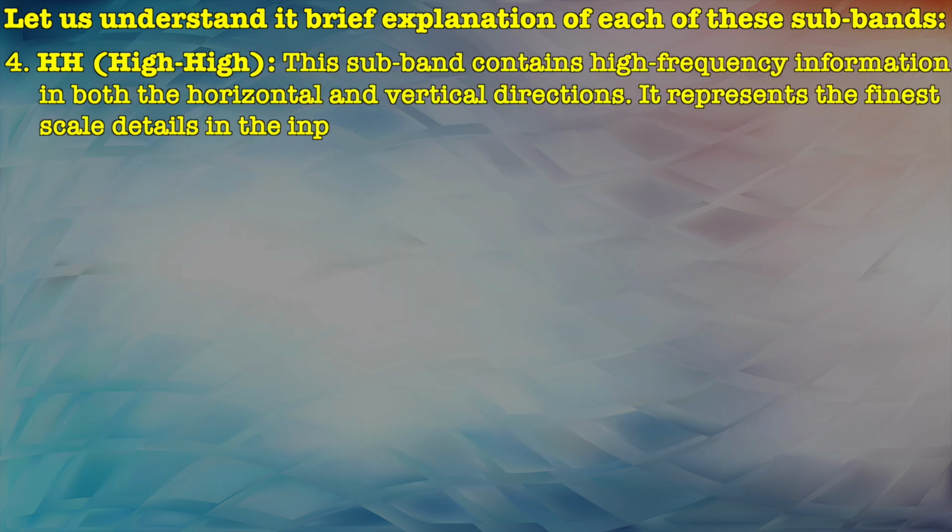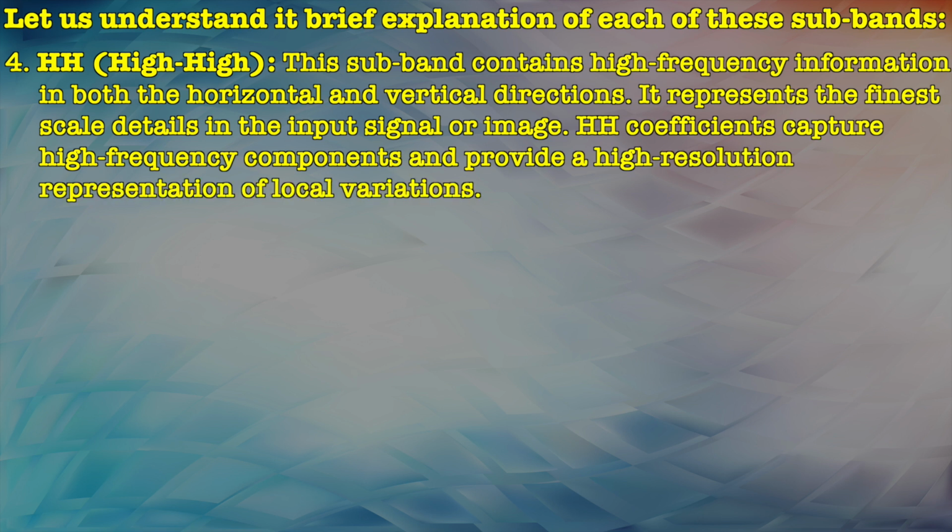The HH, meaning high-high, subband contains high frequency information in both horizontal and vertical directions. It represents the finest scale details in the input signal or image. So HH coefficients capture high frequency components and provide a high resolution representation of local variations.